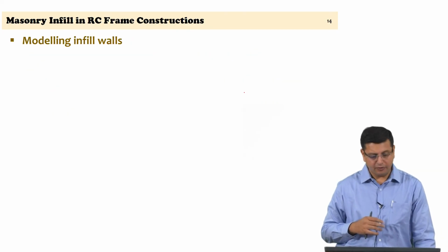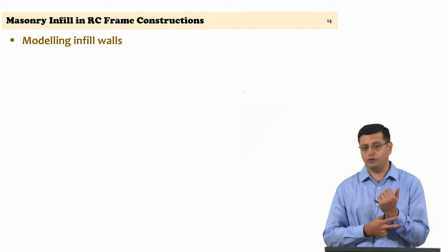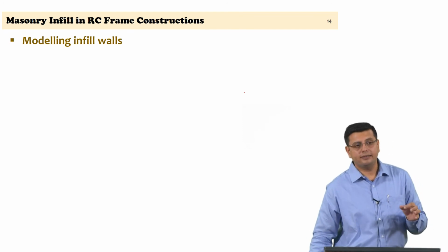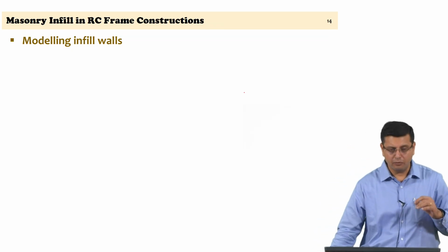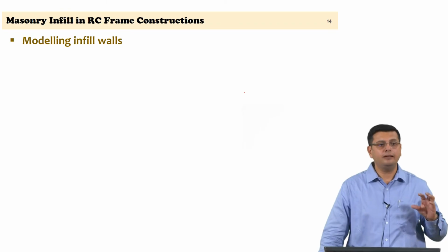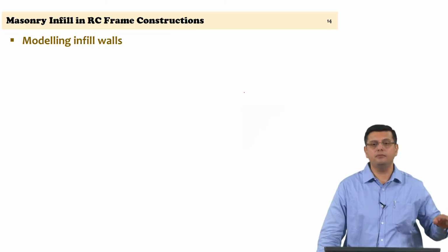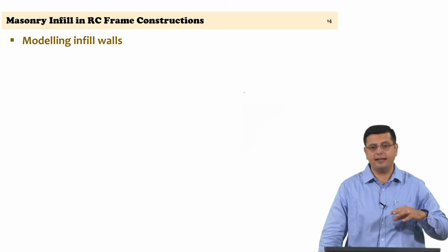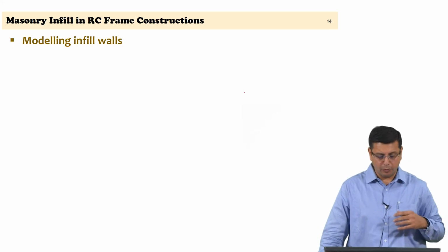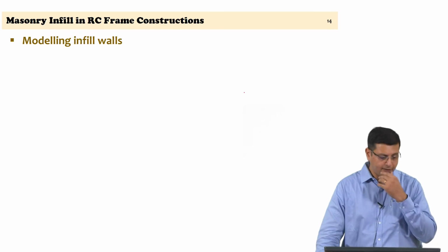Okay. The final thing that I would like to look at is it is required that these infill walls, infill panels are considered in the seismic design, okay, because you have seen the possible effect infill panels can have on the lateral load resisting system in the case of a moment resisting frame itself.